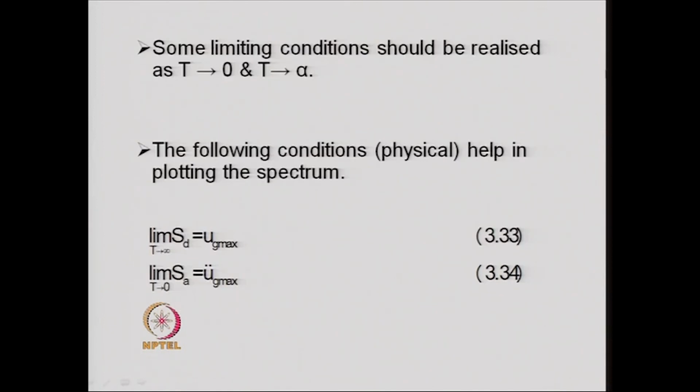So, taking advantage of these two relationships, we are able to plot all the three quantities, that is SD, SV and SA, in a single plot having the logarithmic relationship, or in other words a special kind of log graph.